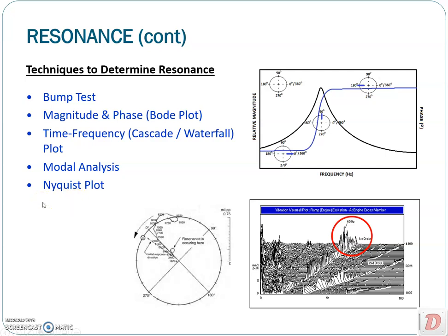Finally, the Nyquist plot or polar plot is another method to represent the vibration magnitude and phase from that transient analysis. This plot could trace a circle in the resonant frequency region due to the phase change in this region.